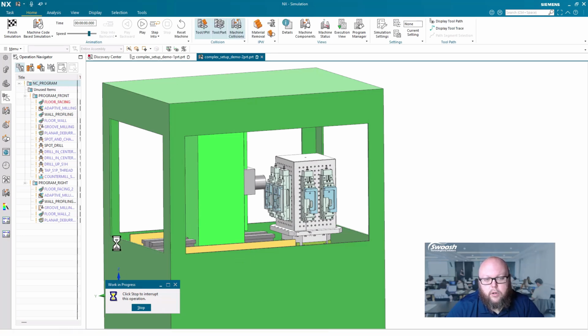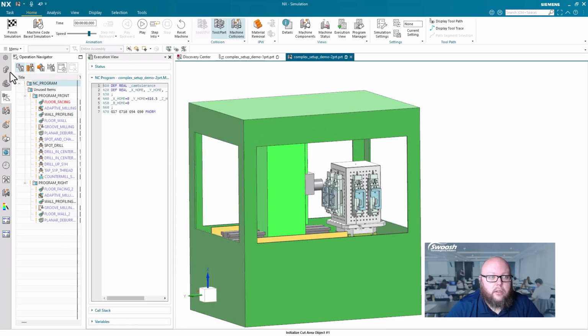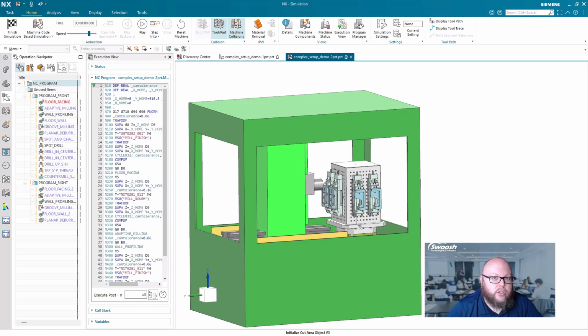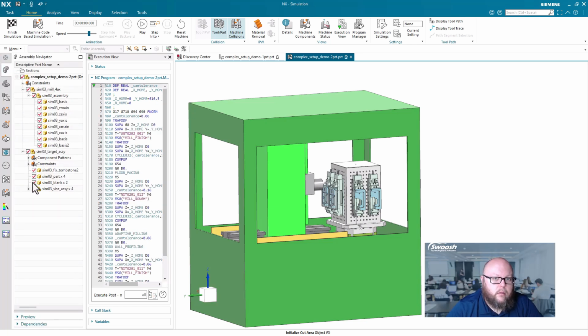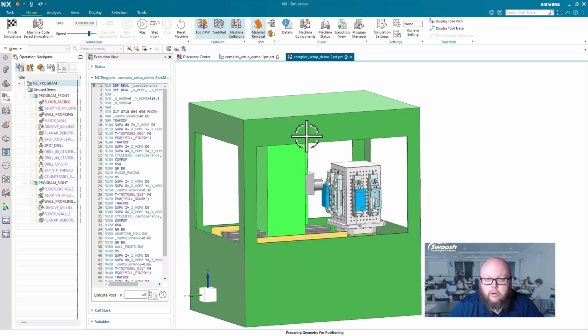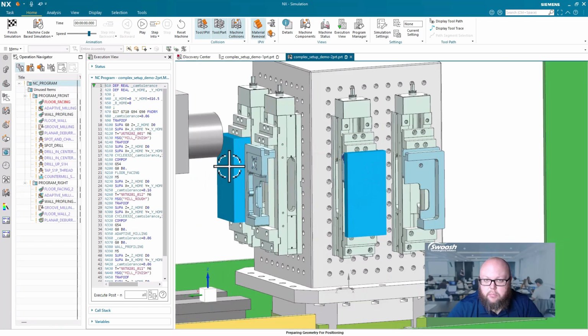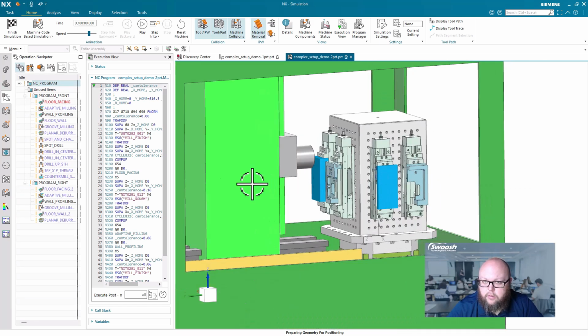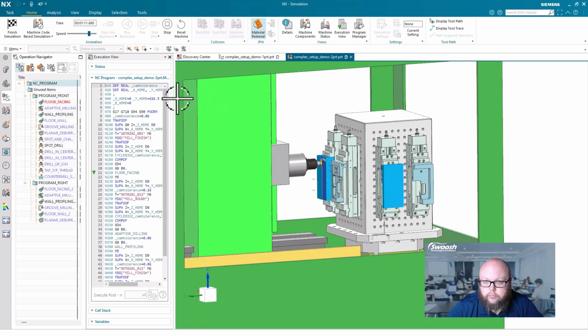Anytime you do this, it's running the post processor right now to go ahead and generate the code. Or it will also inherit the code if it's already been attached to the operations. All right, so now let's take a look. What do we have here? Turn on our material. All right, we see both of our IPWs have been created. Let's go ahead and start our simulation.